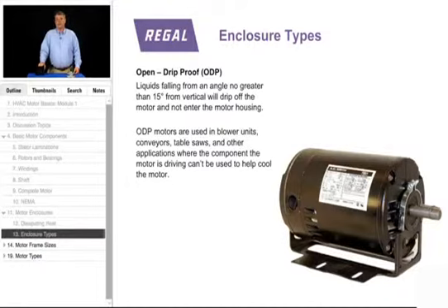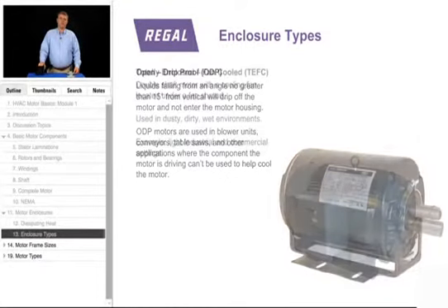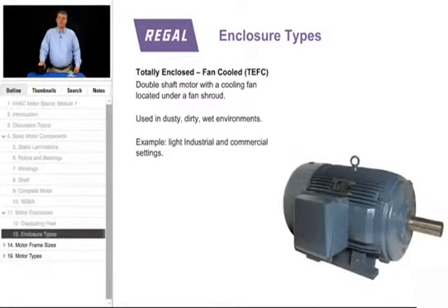The next type of motor is a totally enclosed fan-cooled, or TEFC. This type of motor is really a double shaft motor with a fan on the opposite drive end to help move air over the motor and fan cool the motor. Dusty, dirty, wet environments. Typical application for this motor, light industrial commercial.